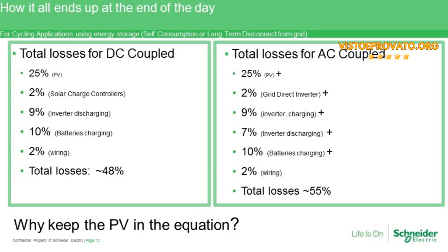Really, floating batteries maybe costs a kilowatt hour a day, especially if they're aged batteries that need a little bit of extra to keep them up at their ideal voltage. But good long-term storage batteries with an AC coupled solution is a really nice way of having that battery-based backup system ready to go, but isn't going to affect that return on investment for just a straight net metering and, say, feed-in tariff program.